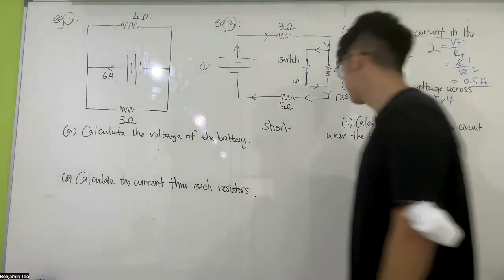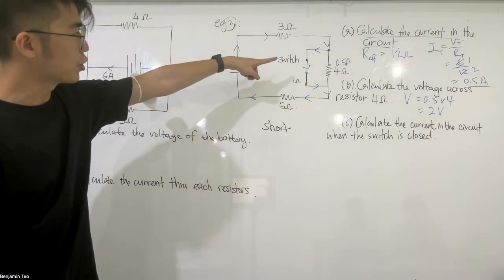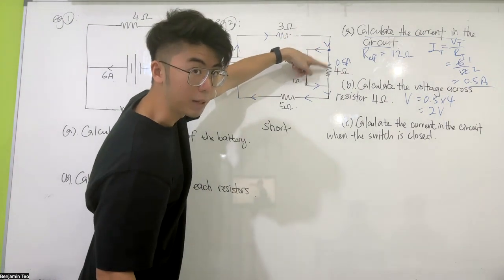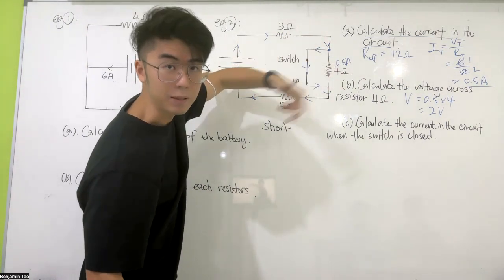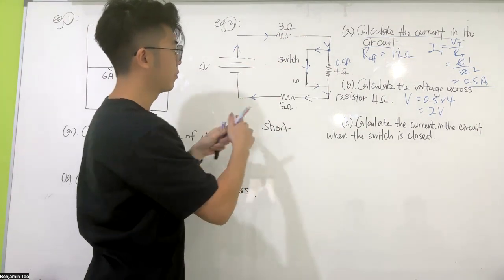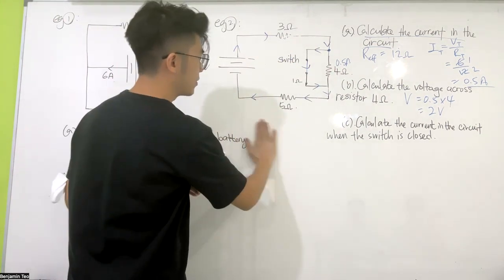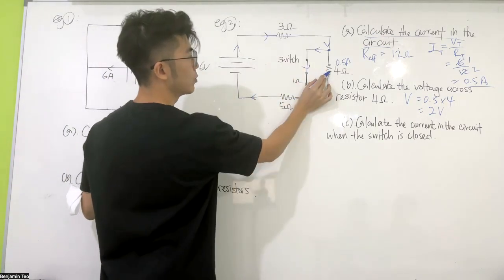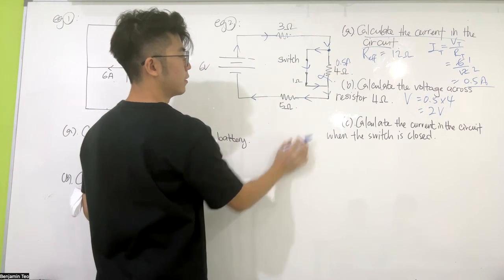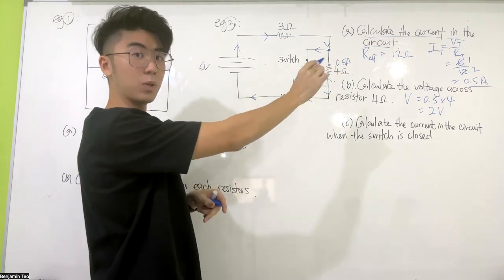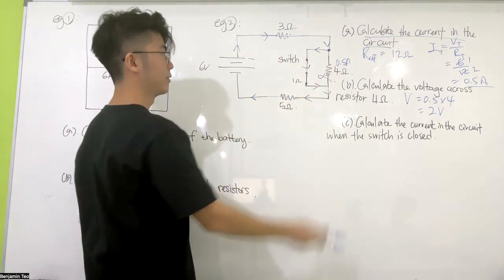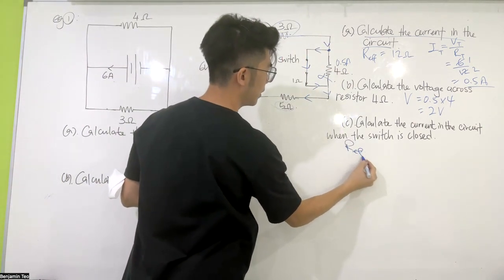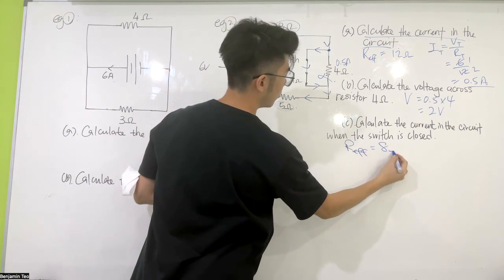Okay. So now we have a short circuit, the current goes here, bypassing this one. It doesn't flow through it. So just skip it. So what is your result? What is the overall effective resistance? Since current flows through this one and this one only, it's as if this one wasn't there. So your effective resistance will be reduced to 8 ohm.